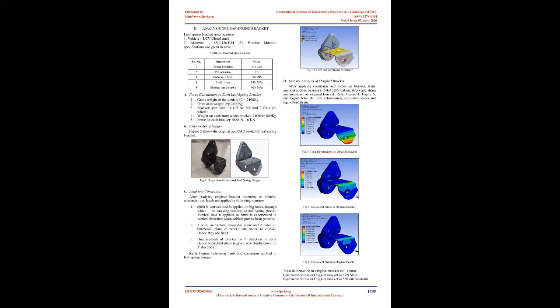Topology optimization is done using FEA software. There are various algorithms used for topology optimization. Most of the optimization software use a density-based approach, in which each element in the design space will have its own stress level and strain energy. Elements having higher stress level, 1, are retained and elements with zero stress level are eliminated unless the overall structure is affected. Topology optimization targets the number of elements to get rid of, which depends on input values given by the designer.